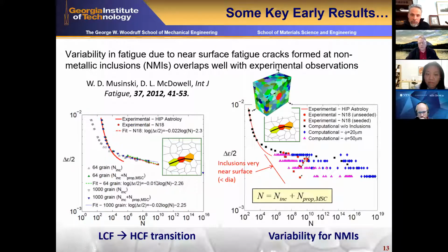what he did was to use that small crack growth law, that da/dN is phi times FIP minus a threshold value, and fit the results in the low cycle fatigue regime, shown here as the red line, and then predict the high cycle fatigue, to form a crack that extends from the first grain into its neighbors, right?